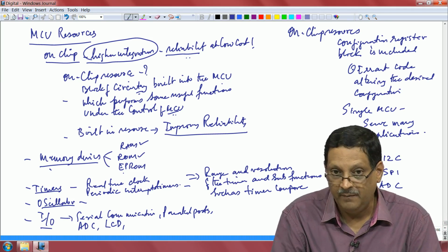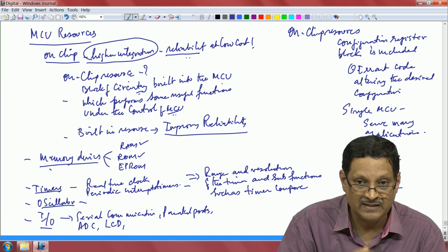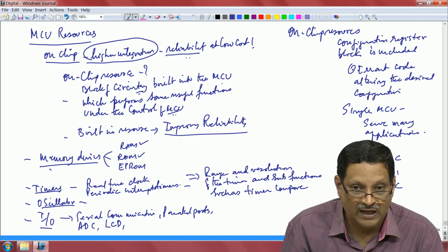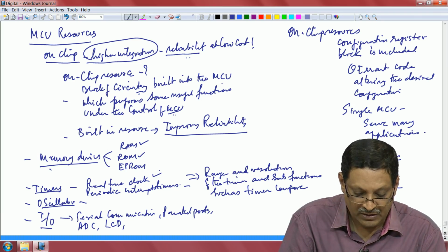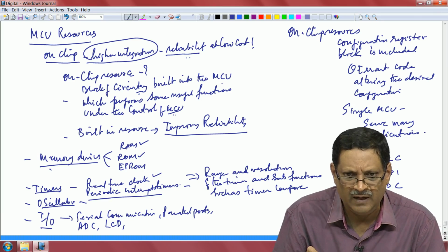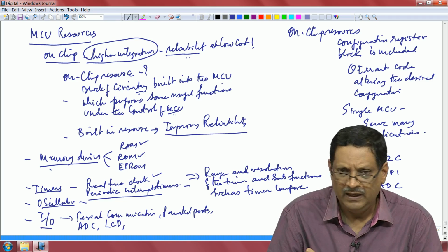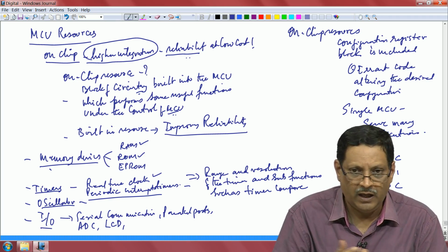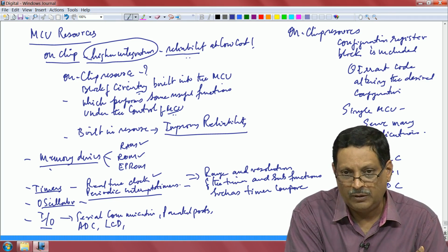Timers, when you say, you talk about real time clock RTC, which is integrated inside the MCU. You can have an MCU without an RTC, you can have an MCU with RTC. So, you can use it for real time clock operations, and you can also have periodic timers for other periodic interrupts. In other words, if you are doing sensing every, let us say, 5 minutes, you need a timer which will interrupt the CPU and say go and fetch data from the sensor, right.